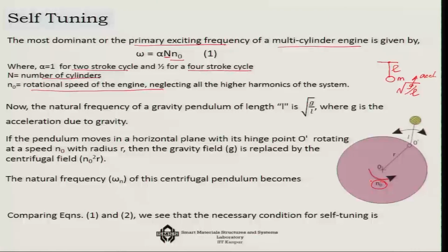Then this acceleration g will be replaced by n0 square r, and the natural frequency of this centrifugal pendulum would then become n0 square root of r by L.